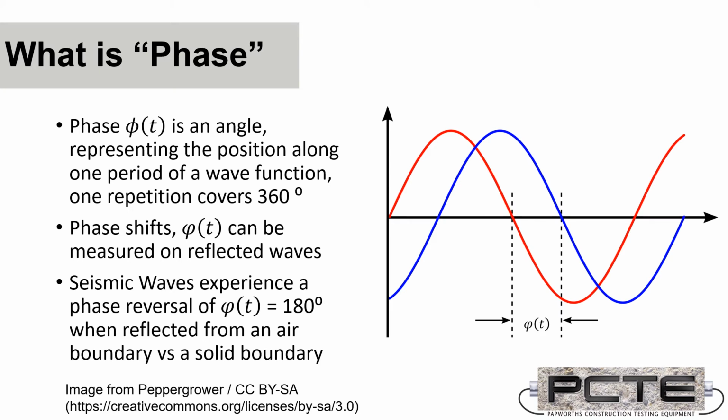So the signal reflected back to the sensors has had a slight difference in where it arrives. If we compare the waveforms, there is a phase shift shown here. We're evaluating that phase shift of shear wave energy, trying to distinguish an air boundary from a solid boundary. That is, a grouted duct from an ungrouted duct.